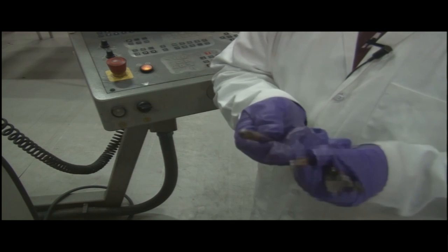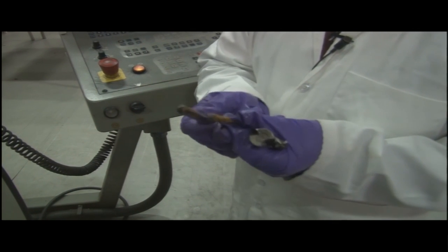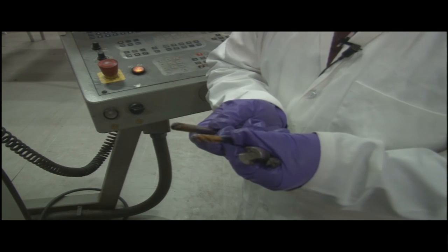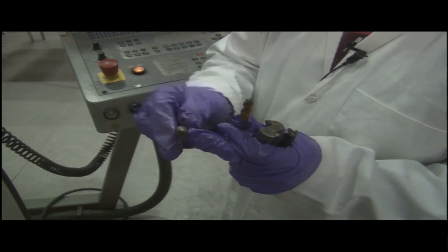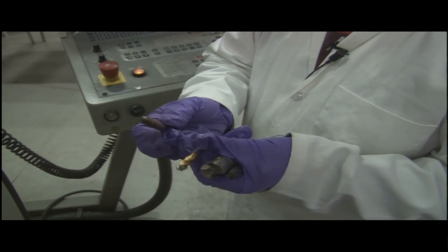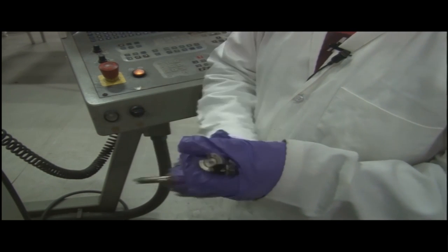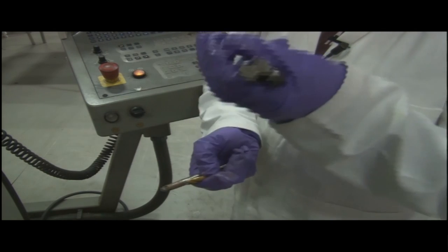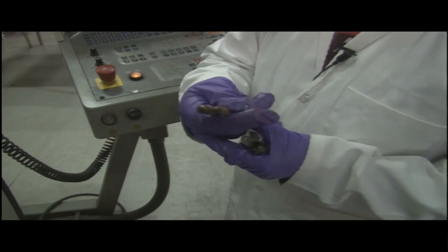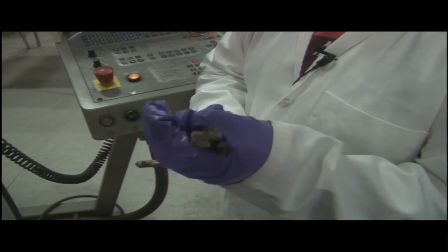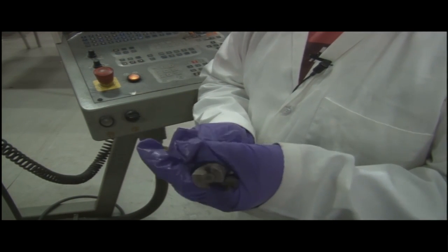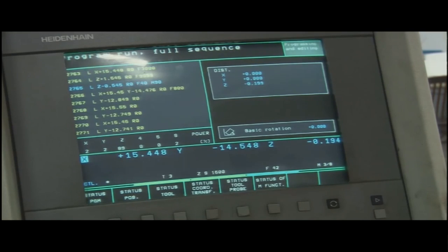These are ball milling tools. Again, one of them is inserted, and one of them is solid carbide. When I say inserted, the inserts are solid carbide, and when I say solid, it is a completely solid carbide tool. Solid carbide tools are obviously very expensive in comparison to the inserted tools. The ball mill is always used for finishing operations, and these mill cutters are used for roughing. Finishing and roughing we have already discussed in the previous lecture.